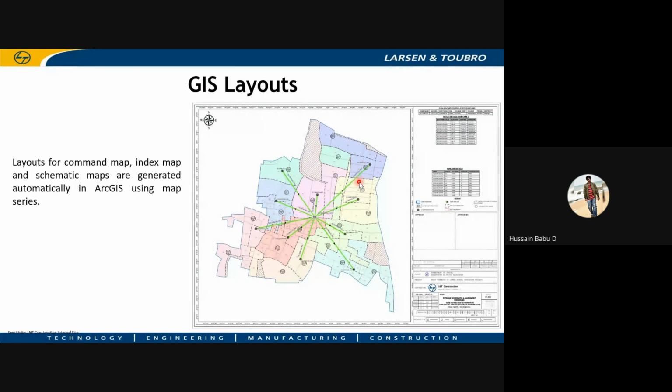As like, this is one check. If you are automating some 2000 checks, then if it goes to another check, these tables are automatically updated based on the pipeline details available for that check. This level of automation can be done on this GIS platform, which is very effective, and we don't waste any manpower just for drafting purposes for the submissions.